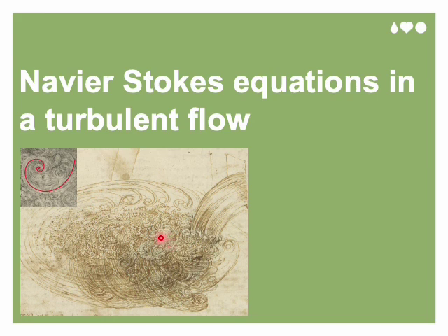I mentioned eddies earlier, which are formed in turbulent flows. Eddies are swirling motions with irregular and chaotic structures that vary in size and shape. They are responsible for transport of momentum, heat, and mass, and may have a size ranging from several meters in atmospheric flows to fractions of a millimeter. By this definition, let's explore how to model turbulent flow.